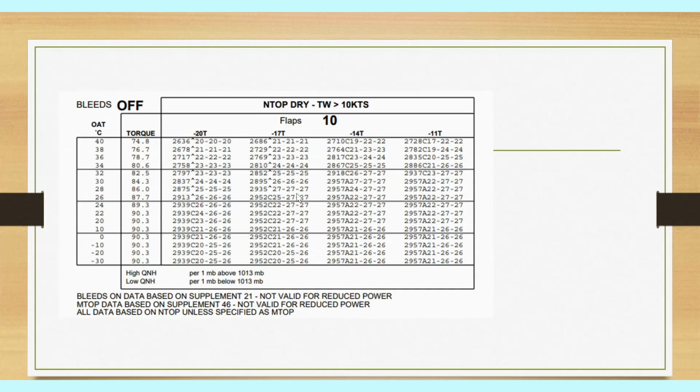And in this table, we are not going to focus on all this jargon here on masses and speeds. We are going to be focused on this bracketed part here, which I actually told you in the previous slides. So again, 25 degrees is between 24 and 26, which is somewhere around 25 degrees. Okay, so the torque for 24 degrees is this one here, and the torque for 26 degrees is this one there, which means that the torque for 25 will be in between the two. So we are going to show here how we can use the method of interpolation.